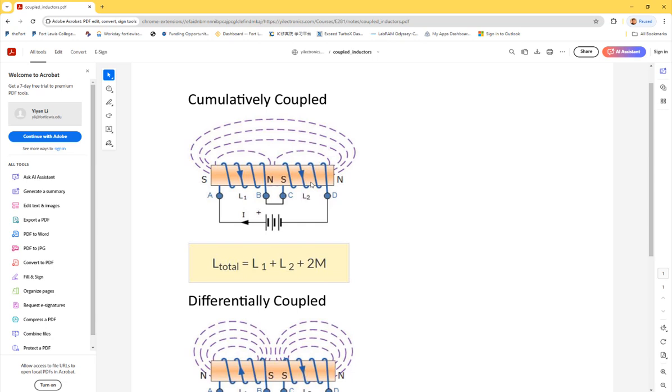If you have an inductor close enough to another one, so they both are generating magnetic field, that magnetic field will cut through the other inductor's metal and will create a current in addition to whatever current is already in there. So it's being generated by the mutual inductance, depending on how close you place them together, right? If you place one in US, one in China, definitely they won't interfere with each other. But if you place them close enough, they will. And it's also depending on...